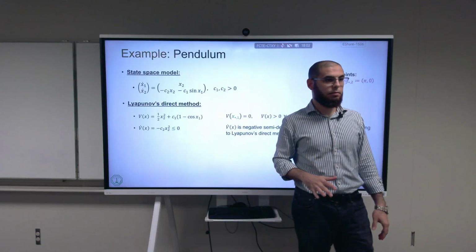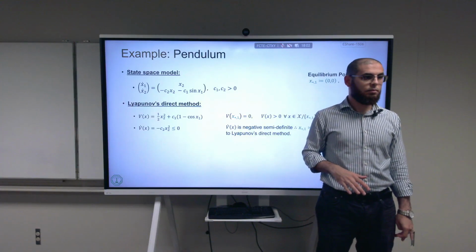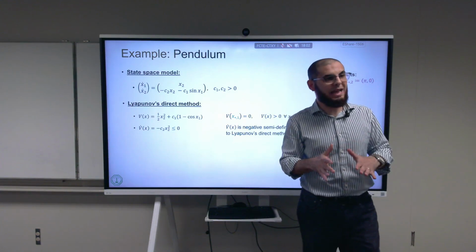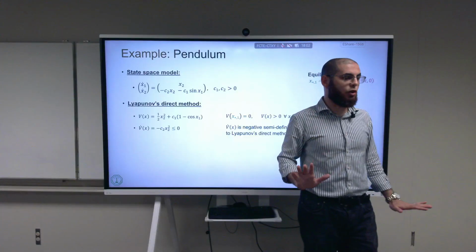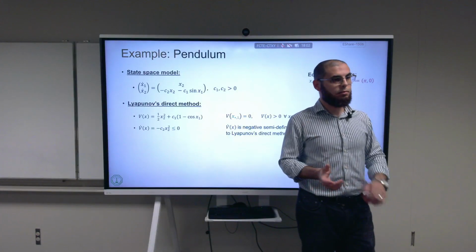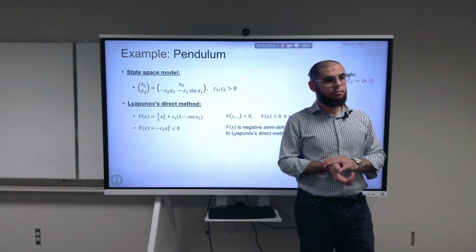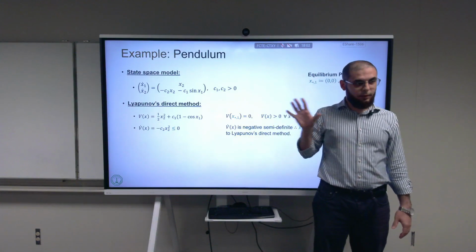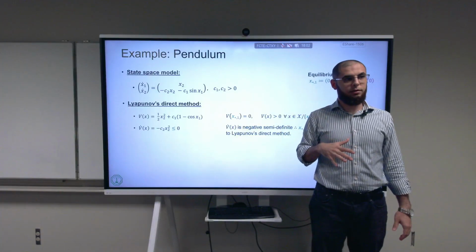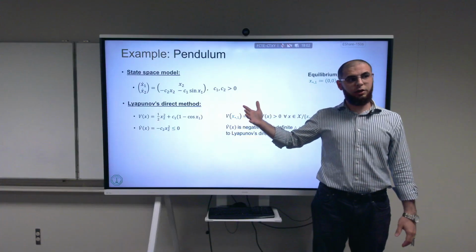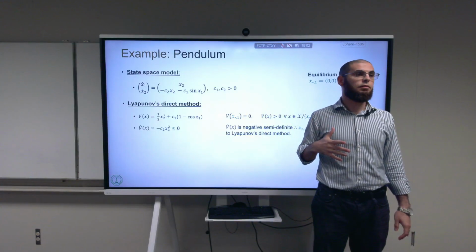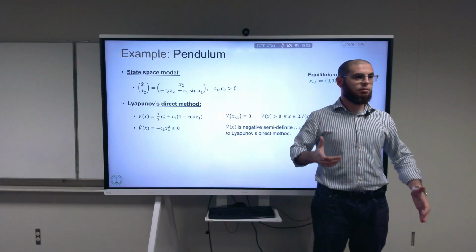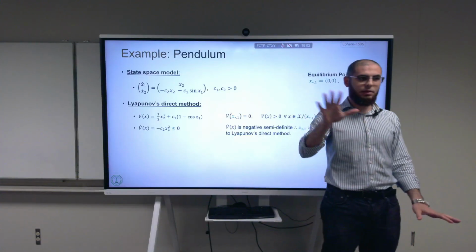We can make a system asymptotically stable. If it's unstable and you make it stable, that's the best you can do. Then it's okay. Maybe that's already a requirement. I think all the systems are asymptotically stable, like they reach stability at the end. Not necessarily. When you go to nonlinear dynamics, things can be very complicated. In nonlinear systems you can have something called a limit cycle. Limit cycles keep on oscillating forever. And hysteresis also plays a role, and things can get nasty.